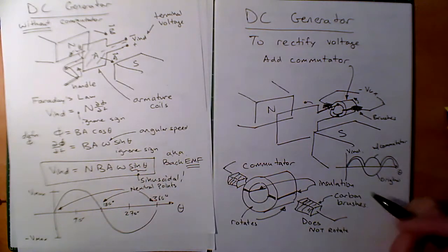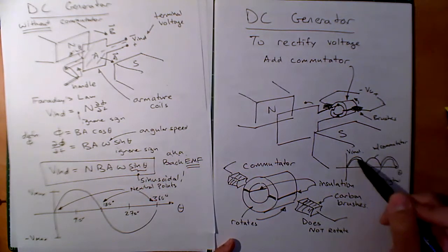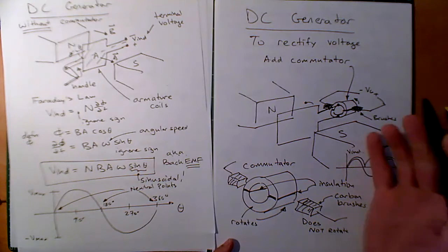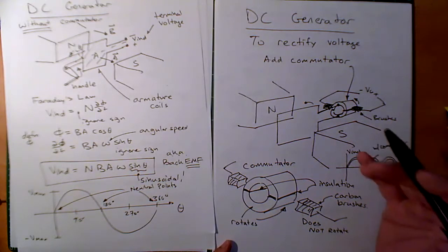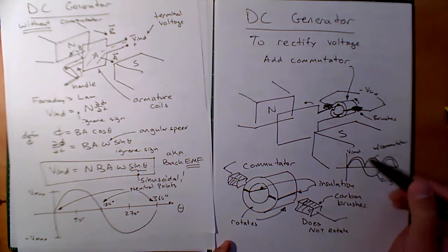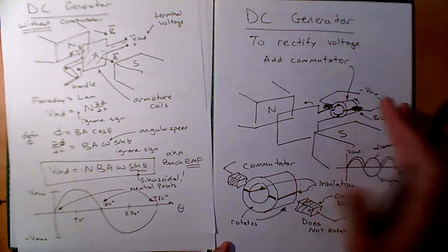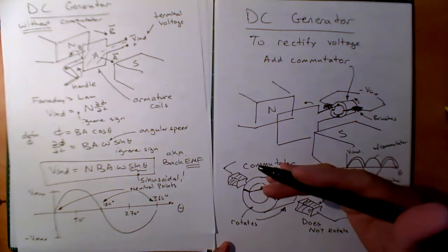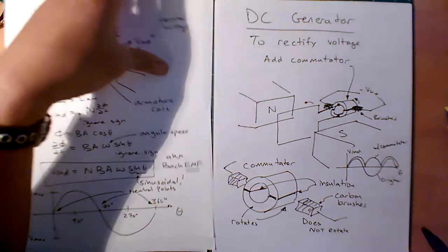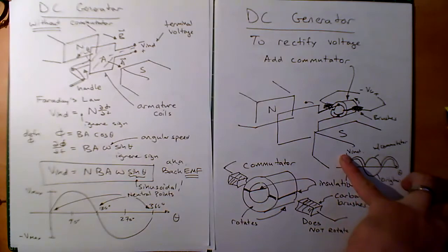Okay, so what would happen? What would happen is this. Here's your original AC current and voltage, right? And with the commutator, it's going to rectify it, right? Just like a diode. Remember in 370, we learned about diodes, how they rectify? Well, this is like a mechanical diode, right? It's going to mechanically rectify. Really cool, right? This is technology that still is in place, and it's technology that worked before we were able to develop transistors reliably. So pretty cool stuff, how creative our forefathers were, right? Okay, let's keep going through here.